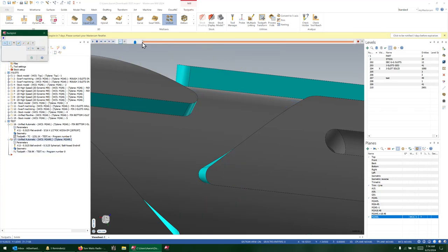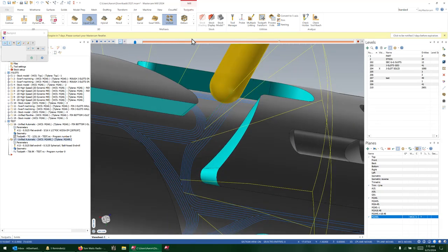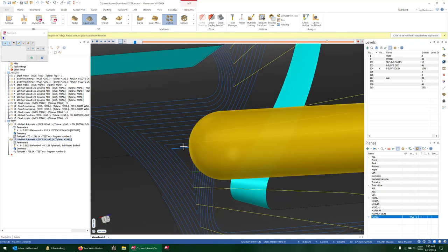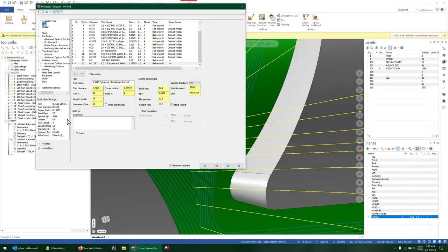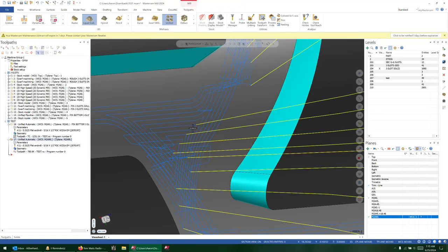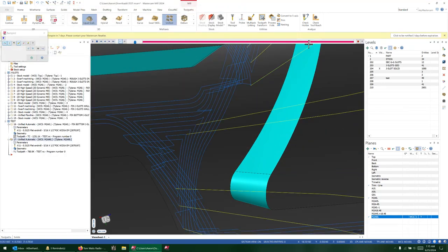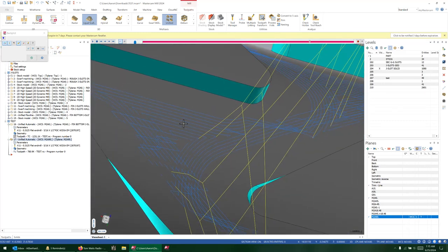All right, so now, of course, going to a ball mill, you don't see that noise coming up because it's not bouncing around kind of front to back. And that's what you were seeing before, it's bouncing from the front of the flat to the end of the flat. Now, what happens if we still want that 4-axis locked motion, because this machine, of course, can't tilt, but obviously this motion is just straight unacceptable, right?